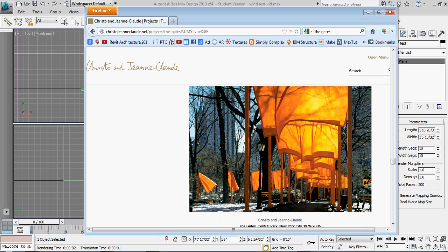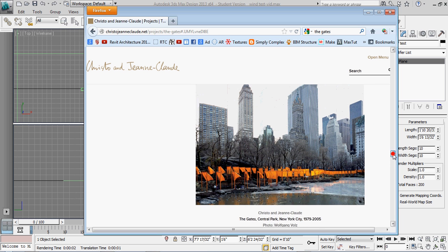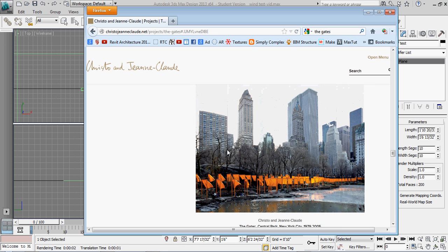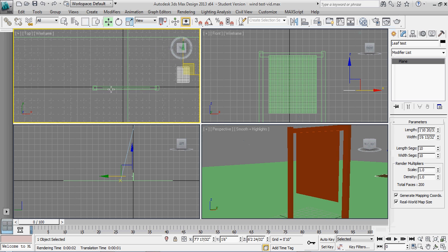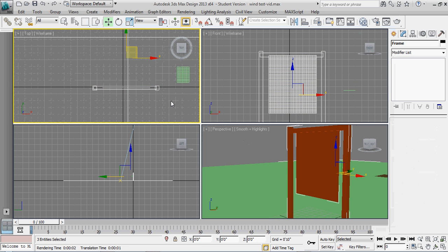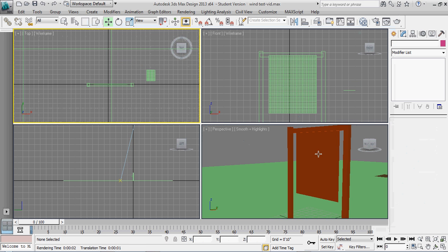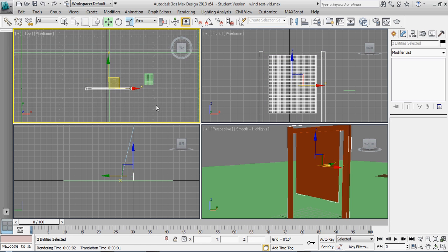And, starting out in cloth simulation, we're not going to look at doing anything as advanced as the pleating or the lining, some of the weighting that happens in the fabric to help it flow a certain way. I just want to get the basic effects for a shot started, and not just these things blowing in the wind, but also the quality of wind passing through and affecting different gates at different times. So we're starting out a scene here with one gate right here, and what we're going to do is go ahead and copy this guy to make a series of gates.